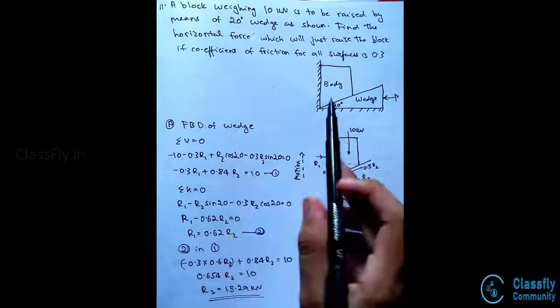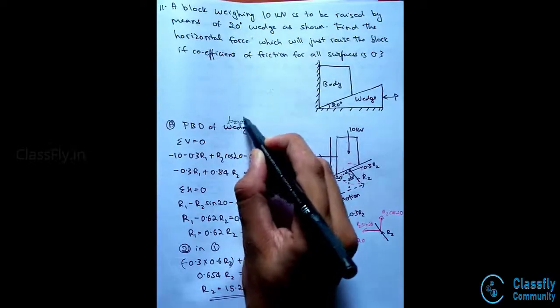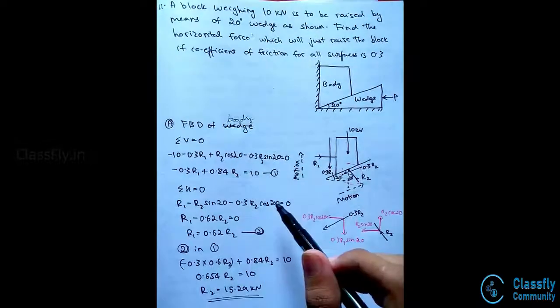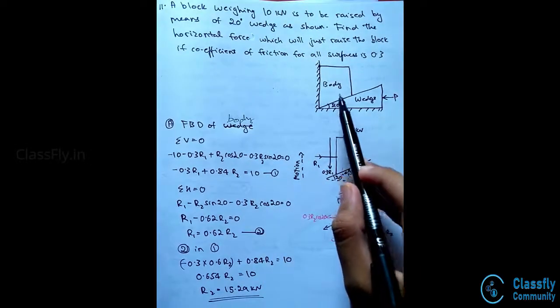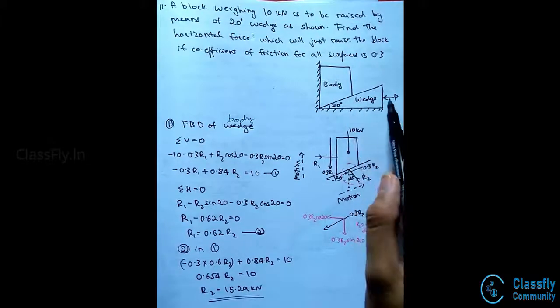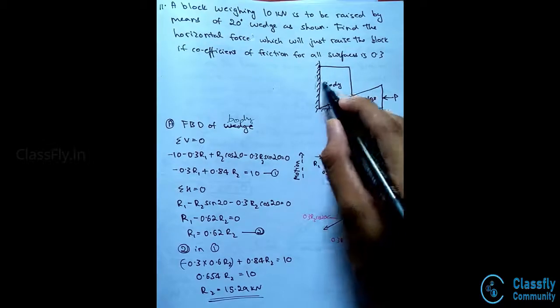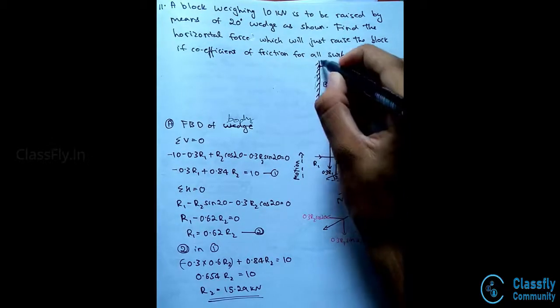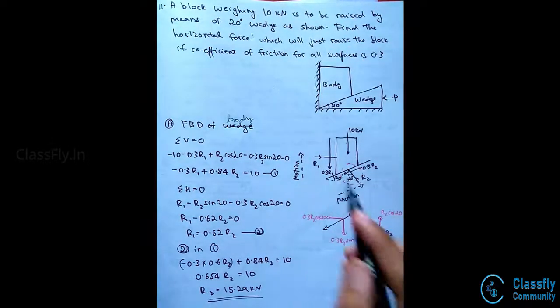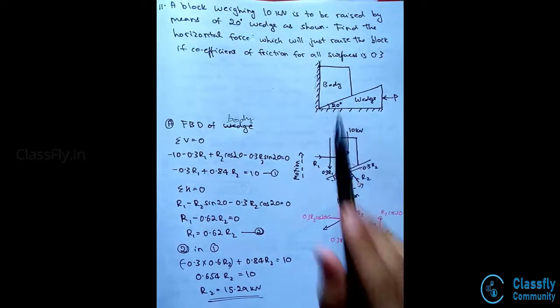Now consider the free body diagram of the body. The body will now have a motion in two directions, that is the motion towards the top of the wedge as the wedge begins to slide, and also an upward motion due to the sliding of the body with this contact surface. Hence, here there will be two frictional and two normal reactions acting on the body.